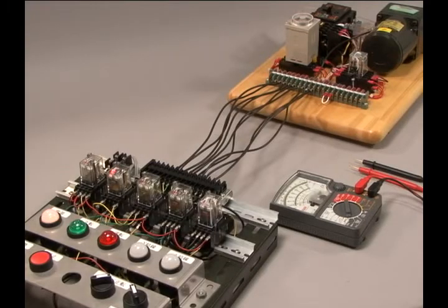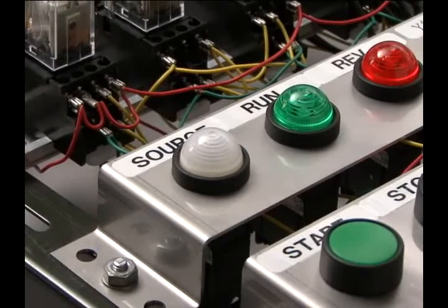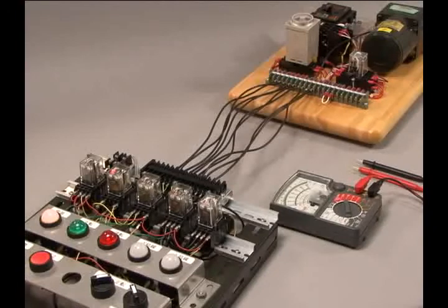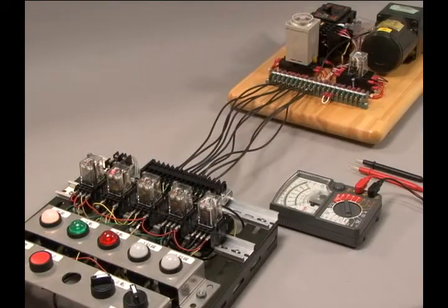Now let's think about how to locate defects with a tester using this circuit diagram. Here, let's assume a condition where the power source lamp does not illuminate, even when the MCCB is turned on. First, let's check the fuse. You can usually determine the state of a glass tube fuse by looking at it. If visual confirmation is not possible or is inconclusive, voltage can be measured at the output side of the fuse. Even if only one fuse is blown, voltage at the output side will be zero.